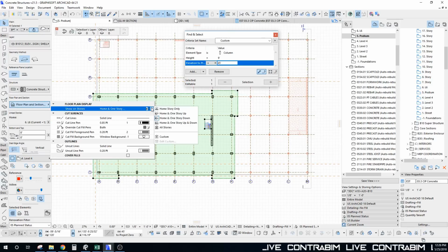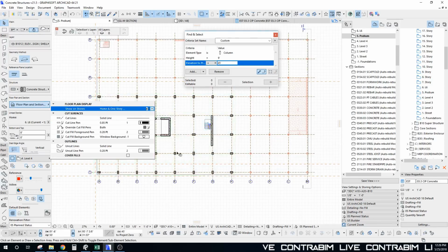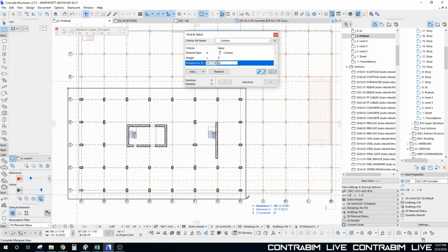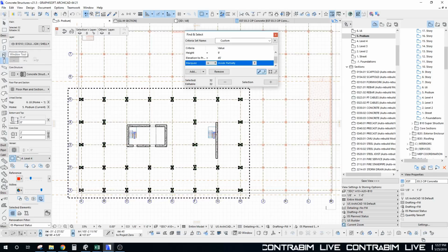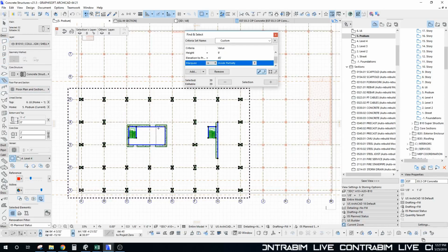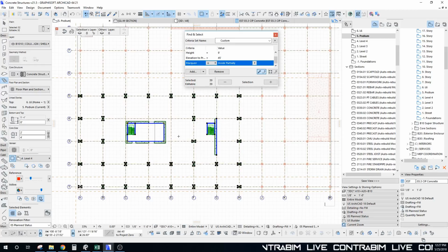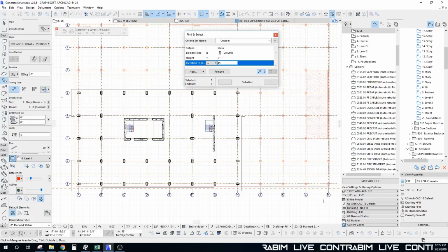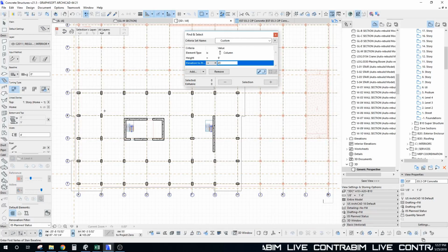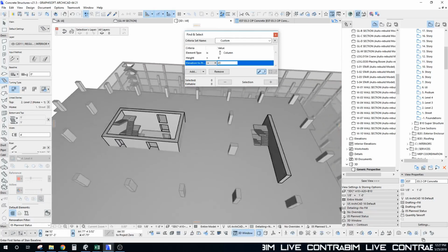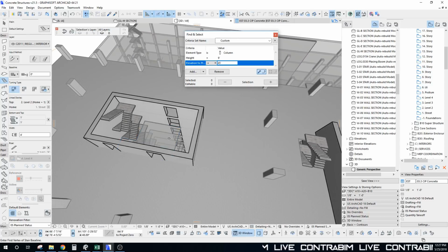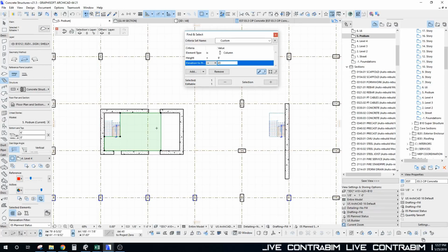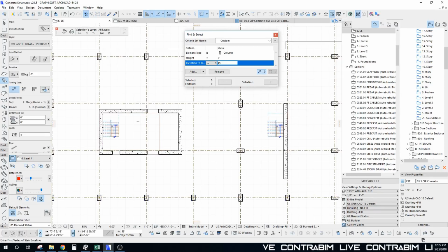So this is showing on both those. So I'm going to do home story only just to make it a little easier to understand what is where. So I'm going to pull up my columns, my walls, my stairs, do a Control C. We're going to paste those in. Okay, so we're moving up, and I also need that interior slab. So I'm going to grab that, pull that up.